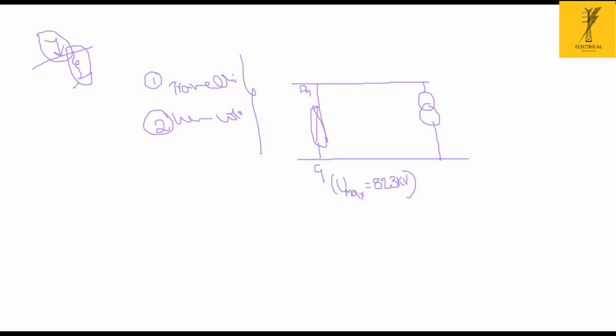The bigger content will be discharged through flashovers in the insulators, or it will hit the shield wire and directly enter the ground. So the lightning arrestor will face surges maybe due to the back feeding of a fault from the ground, the back flashover, or maybe a sudden rejection of loads.